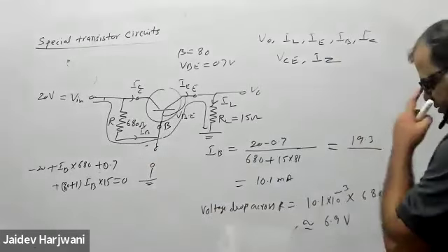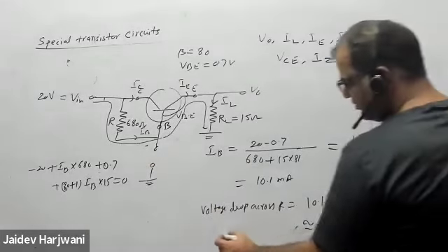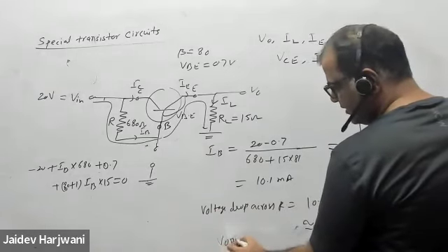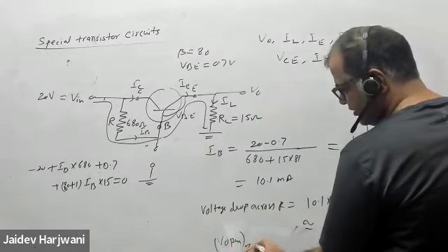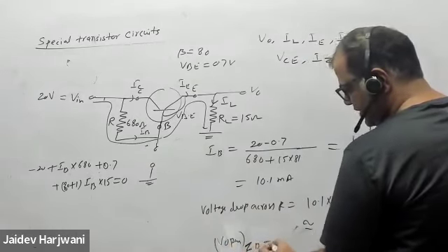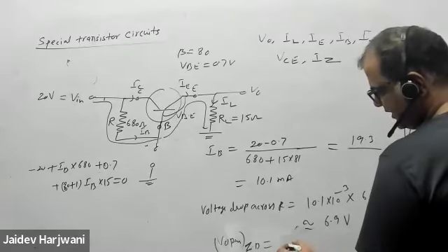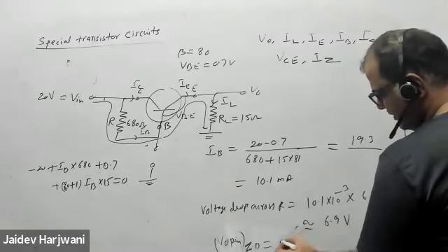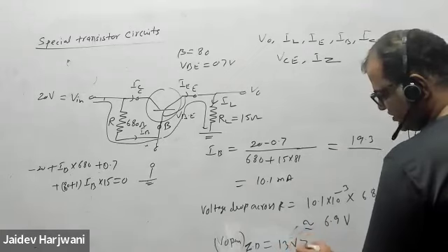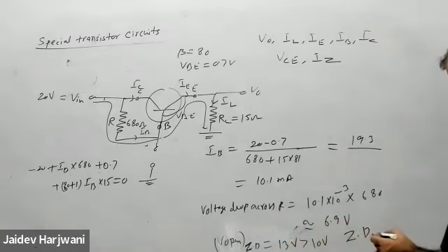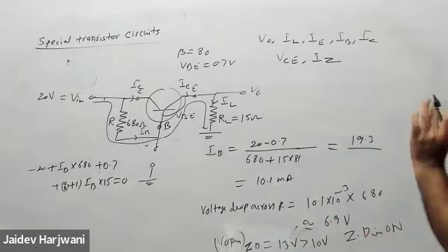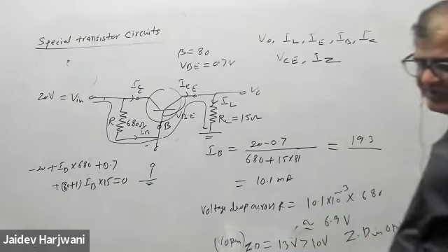Okay. So open circuit voltage across Zener diode is greater than, this is 13 volt coming, I'm roughly writing, which is greater than 10 volt. That means Zener diode is on. So this first part is just for checking.